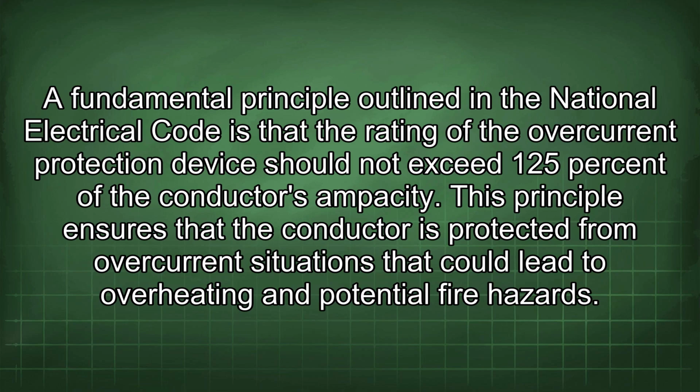A fundamental principle outlined in the National Electrical Code is that the rating of the overcurrent protection device should not exceed 125% of the conductor's ampacity. This principle ensures that the conductor is protected from overcurrent situations that could lead to overheating and potential fire hazards.